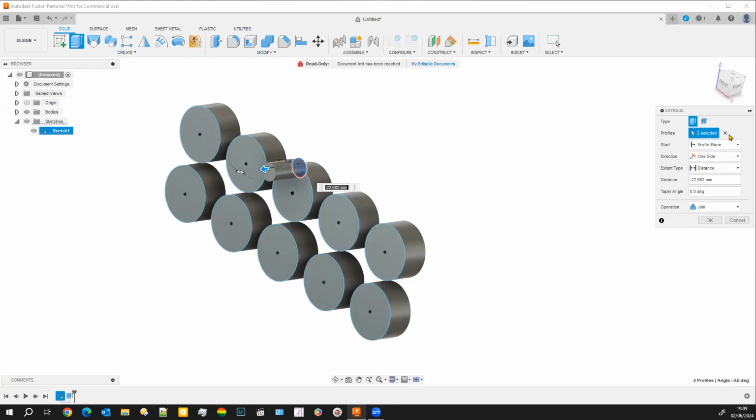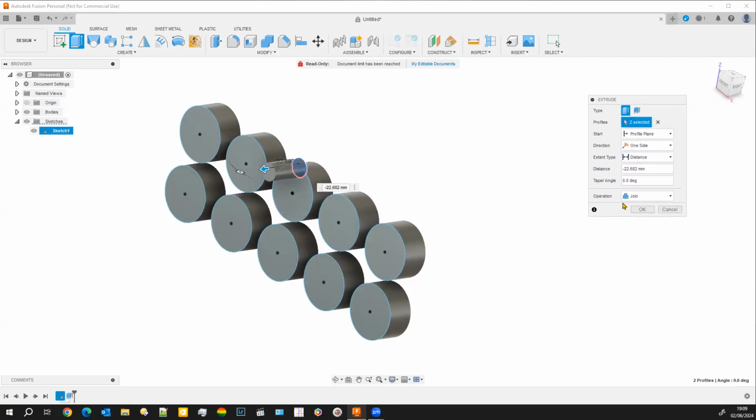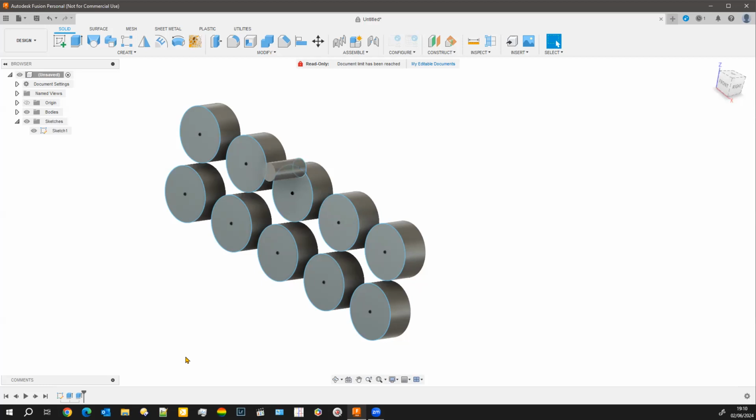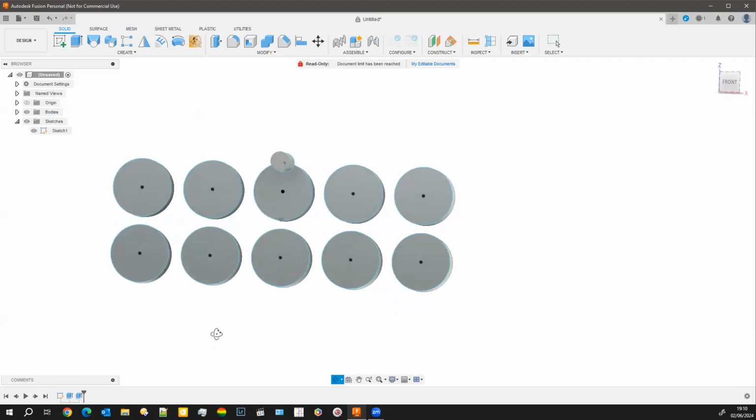The other thing with things like this as well, I may have mentioned it before, it will tend to default to cut or join. Sometimes it's good to create a body. A body is much more maneuverable later on than having a cut or join. But that's not what I want, because I actually want the pattern to be reproduced, and it's not reproduced.